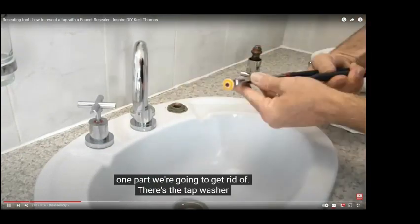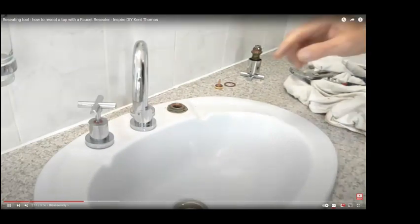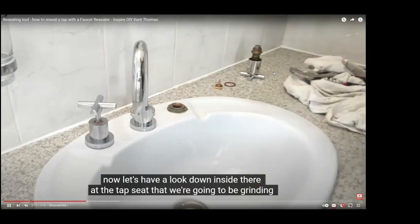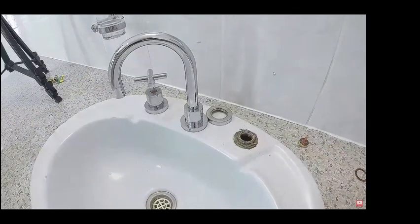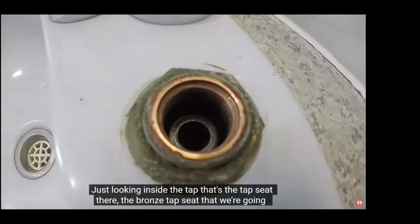All that should come out. Usually the jumper is trapped in there. It shouldn't really float and fall apart, because sometimes water gets behind it and it causes a sort of water hammer type effect. Sometimes they do just sit loose like that. It depends on the design of the tap.